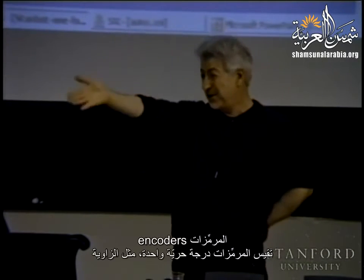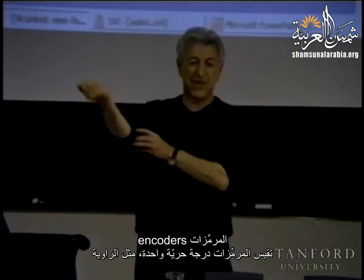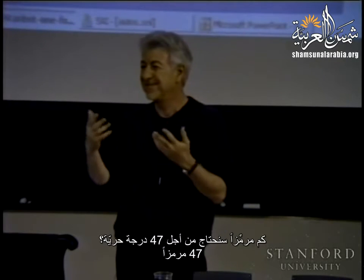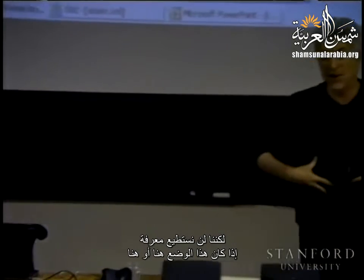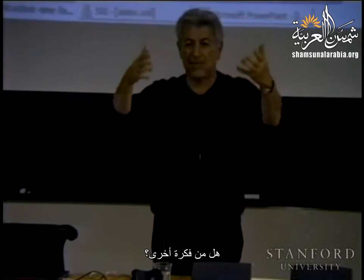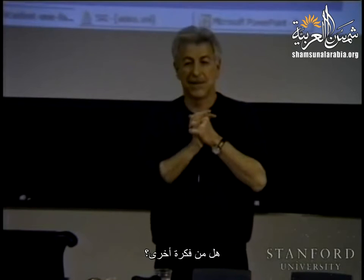Another idea. We need something else. Encoders, yeah, encoders. So encoders measure 1 degree of freedom, just the angle. And how many encoders do we need for 47 degrees of freedom? 47. Now, that will give you the relative position, but we will not know whether this configuration is here or here, right? So you need a GPS to maybe locate one object and then locate everything with respect to it. Or any other idea to locate?